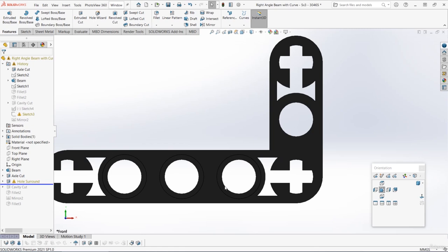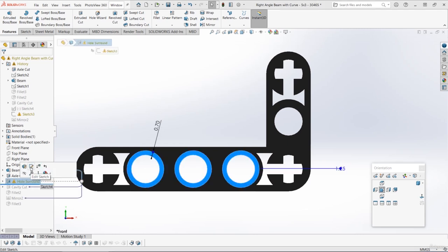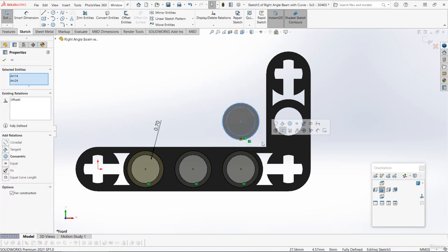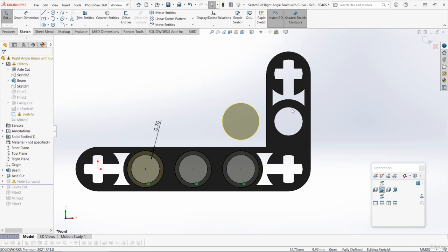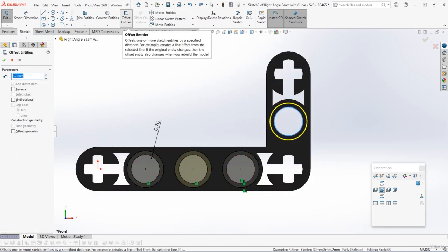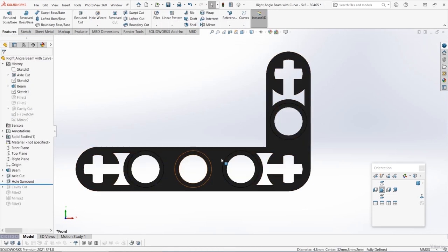So when you do that, you'll probably find that you've got some kind of error on the sketch. That's just because we've changed the number of holes in the model. So let's click on that feature and edit the sketch underneath it. We can just delete that extra circle that we don't need, and then let's just add in this 4th one here. So let's just select that circular face and let's offset 0.7 like this. And then press OK, and we've now cut out all of those rim cuts correctly.